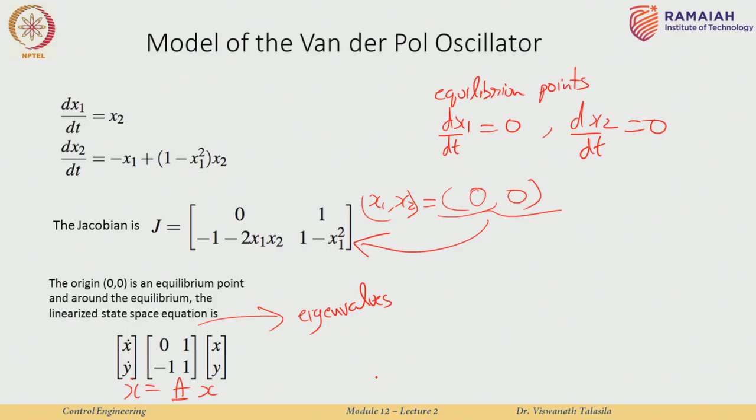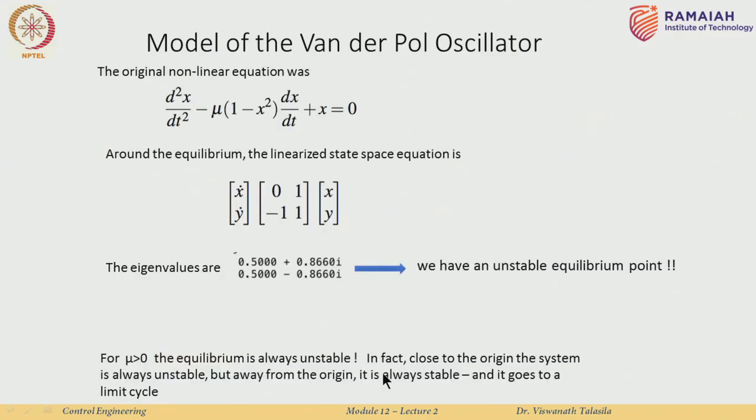Similarly, compute the eigenvalues of the system, and you will see where they are. If you look at the S plane, or the pole-zero map, you will find the eigenvalues are over here. And what have we learned from basic controls? That if the poles are in the right half plane, you have an unstable system.